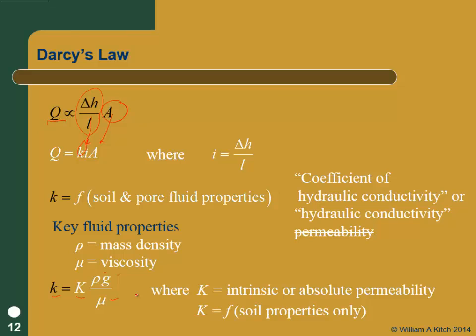to change the properties of the petroleum, and it's going to flow differently. So when you talk to petroleum engineers, when they talk about permeability, they're talking about big K, which is the intrinsic permeability, which is a function of the material of the matrix. So fracking, for instance, changes big K. Pumping steam into the ground doesn't change big K, it changes little k though, because it's changing the viscosity of the material. So we should call this thing hydraulic conductivity.